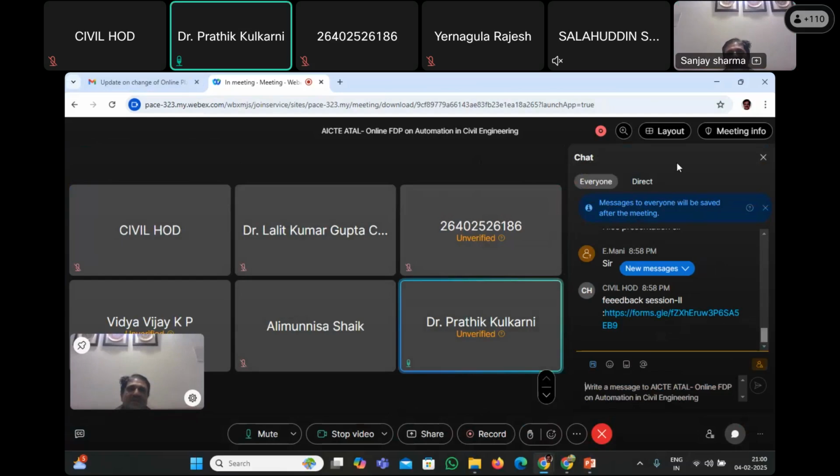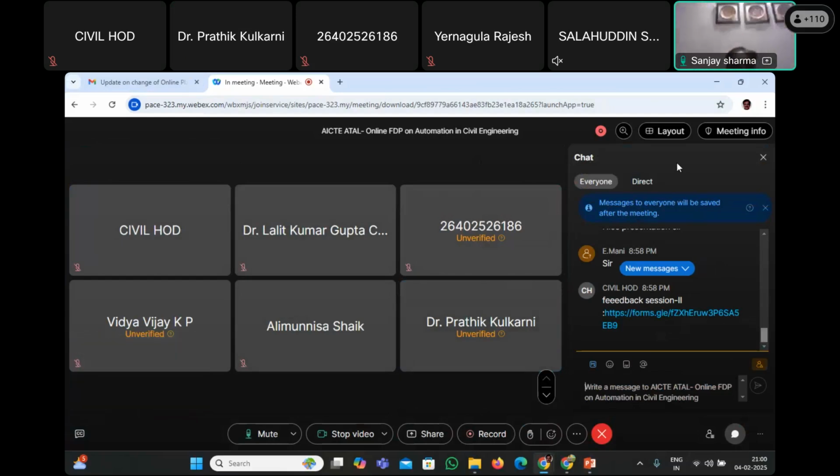I just wanted to know the difference between the resistivity meter and the half cell potentiometer. Both give the corrosion. Half cell works on the principle of voltage measurement, because current is passed, and we see how much voltage is being utilized for passing that current. So the half cell potential meter is measuring the voltage, whereas with resistivity, we are measuring the resistance to flow of the current.